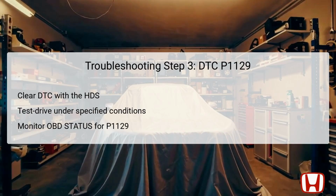Following this, conduct a test drive under specific conditions. The engine coolant temperature must exceed 158 degrees Fahrenheit, 70 degrees Celsius, and the engine speed should be held between 1400 and 6800 RPM in the fifth transmission gear. During the drive, maintain a steady speed between 55 and 75 miles per hour, 88 to 120 kilometers per hour, for 10 seconds before decelerating with the throttle fully closed for another 5 seconds.